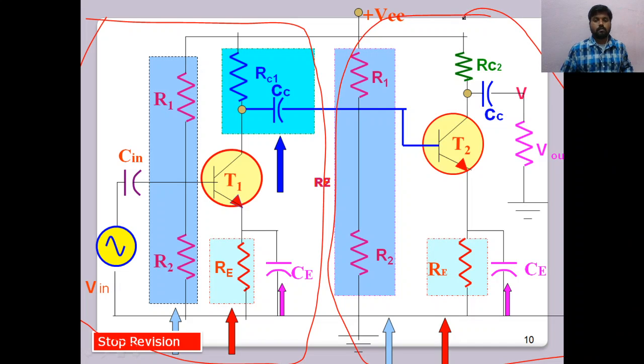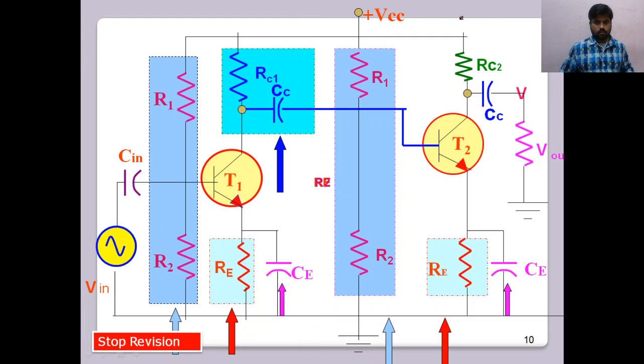These two are now cascaded. So we know all the components, that is R and C. These two in combination give the RC coupled amplifier. Why is the RC coupled amplifier called so? Because the coupling elements used are resistor and capacitor, that is, a collector resistor RC and coupling capacitor CC, so it is called an RC coupled amplifier.